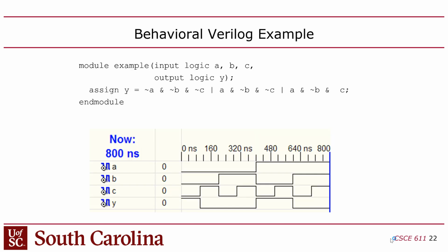Are modules concurrent as well? Yes. So if you instantiate modules structurally, like instance modules and connect them, they're all running concurrently. And by the way, just so you guys understand, the modules are just fake. They're just for designers, they're for humans. Because when you synthesize this onto the hardware, it flattens the hierarchy. So when it becomes physical hardware, the modules disappear, right? Because everything gets kind of inlined into one gigantic rat's nest of wires.